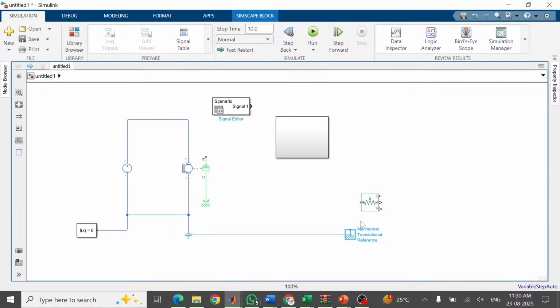In this block we need to connect with our vehicle body section. Please go to your vehicle body section, copy these two blocks, cut them, and keep them the same. One by one we can design, so don't be confused. I will give you the complete explanation overall. Finally, take the ideal translation motion sensor. With this we can calculate the speed and everything. Connect the reference, and connect this R part in this area.